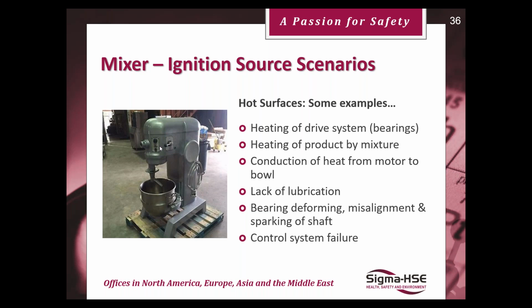Whether it's effective or not, that's what you put in your table. Say, what are my safeguards? That's why it's not effective, not credible or not likely. Yeah, there could be a lack of lubrication. So maybe the motor doesn't have the lubricant and it gets a little bit hot and conducts the heat into the shaft or into the vapor space of the mixing bowl where the flammable atmospheres are.